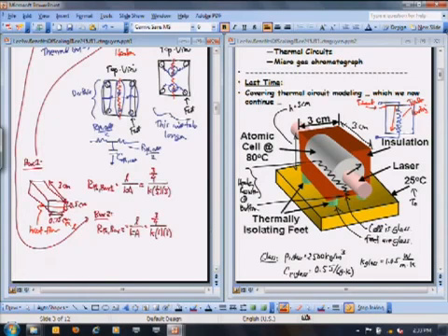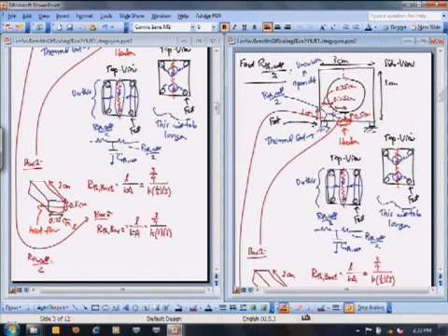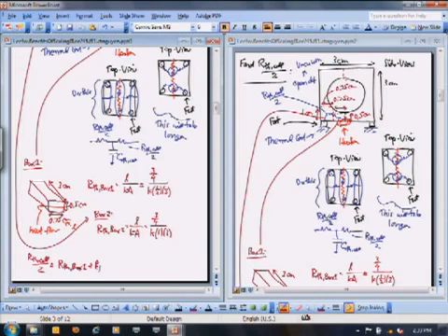So in the end, the thermal resistance across both of these things is the thermal resistance of the cell divided by 2, because it is half. Actually, why am I doing this? I should be doing this. It is half the thermal resistance, this side of the cell. That now is just going to be the sum of these two thermal resistances: R thermal box 1 plus R thermal box 2. If you just sum these together, that ends up being equal to 3/8 times 1 over K.